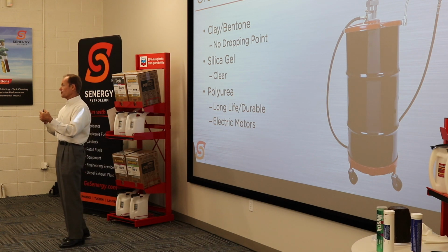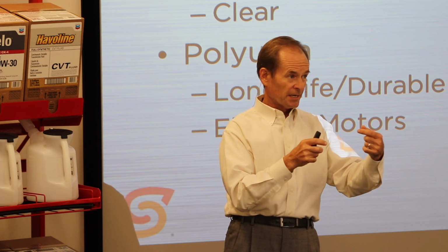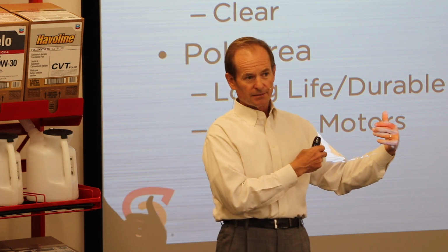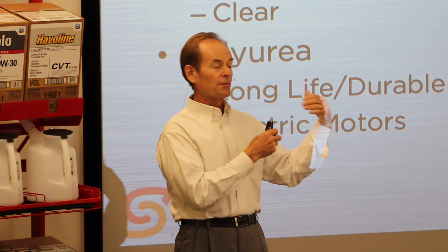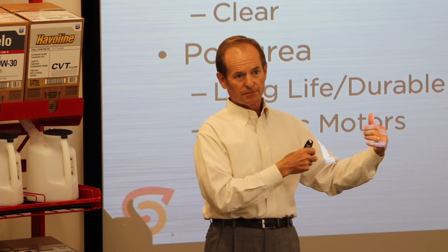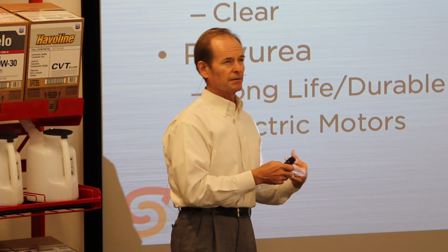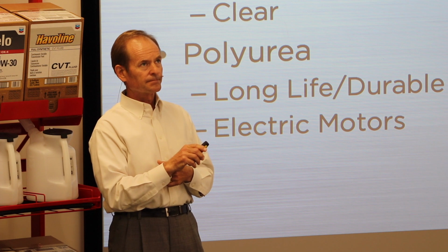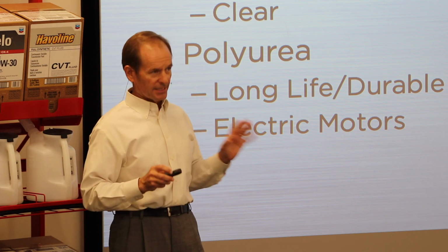Electric motor greases also don't use EP additives, those sulfur phosphorus types, because again, if those got on the windings, they attack copper and yellow metals, right? So that would be another recipe for disaster. So they don't put those in electric motor greases, the sulfur phosphorus kind of additives. And I'll mention electric motors, we've got a picture or two later on as well. All right, so those are your primary non-soap thickeners.